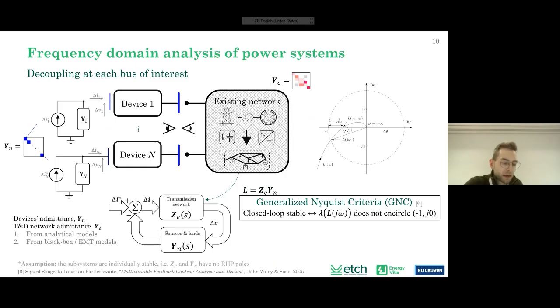In both cases, you get a right half-plane pole in the admittance representation of the MMC at the origin. But in this case, you can deal with it if you just do an indentation around this point on the imaginary axis. And then you can still employ this framework, where you just look if the eigenloci encircle your critical point.